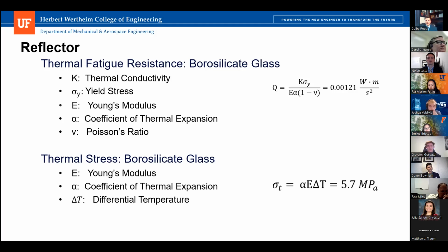Looking into the biggest differential temperature found in the Mojave Desert last year, it was in June, about 55 degrees differential temperature from the morning into the evening. We played that into the factor of soda lime glass, and we found that the expansion would be about twice that of the borosilicate glass. That's why borosilicate glasses tend to be more used in cookware and things like that.